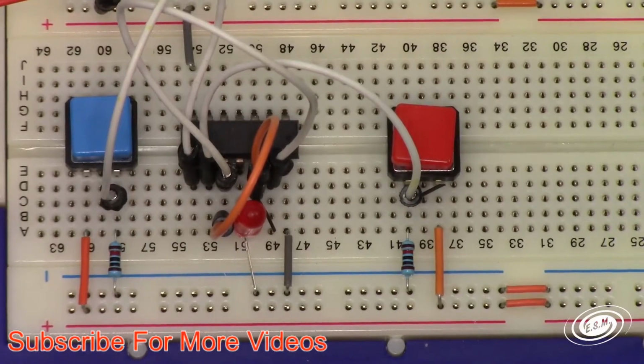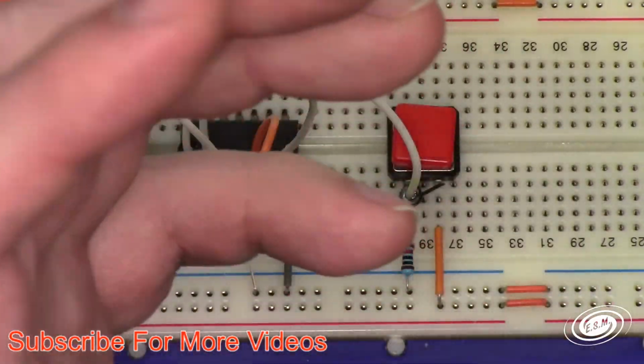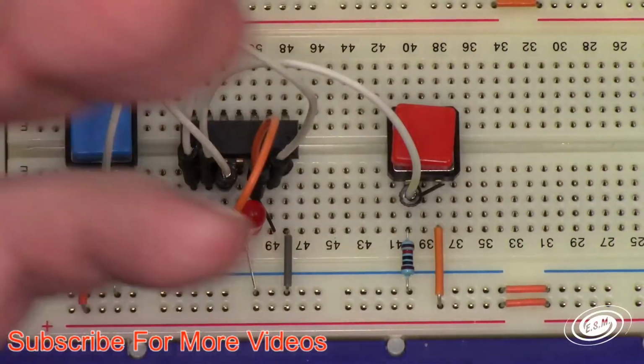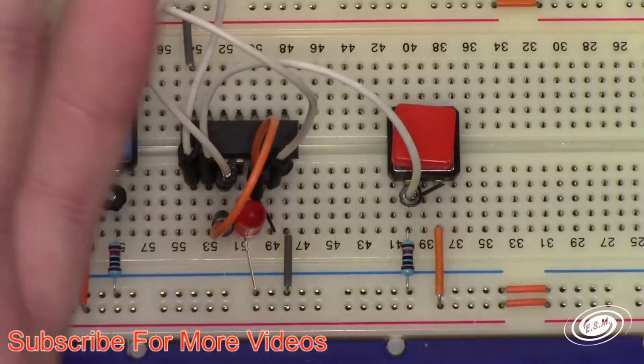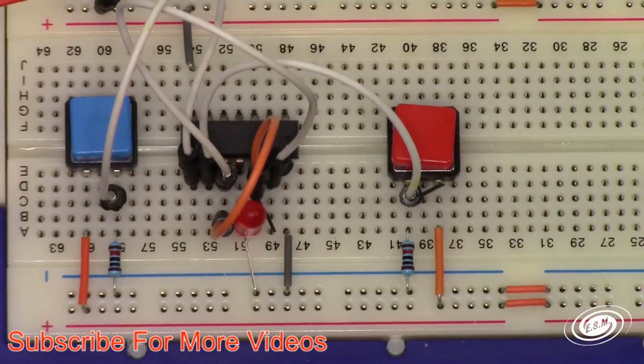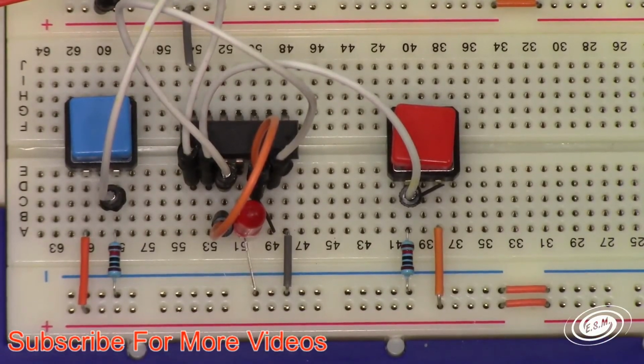And you know, these are old chips. These are chips from the 70s, 80s, and 90s. So having only 4 gates on a chip, that's not a lot. Modern day chips can pack a whole bunch of logic circuits on there, and you can get combinational logic that uses the NAND gates to give you AND gates on a chip. But if you have simple circuits and you need an AND gate, you can use 2 NAND gates. And there are other ways to combine them into different operations. But this is going to do it for this chip.